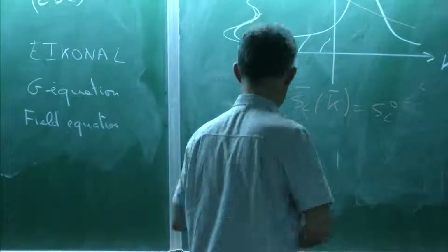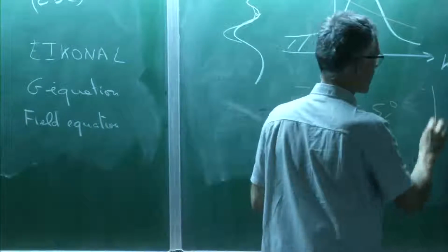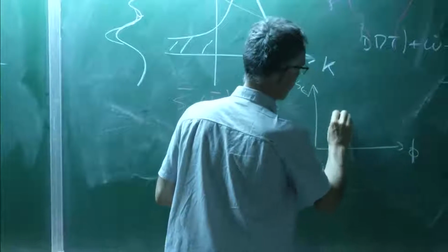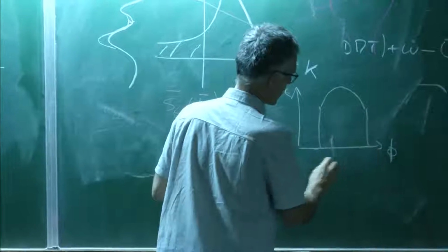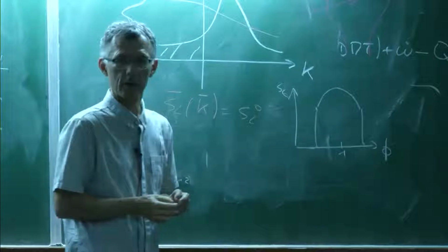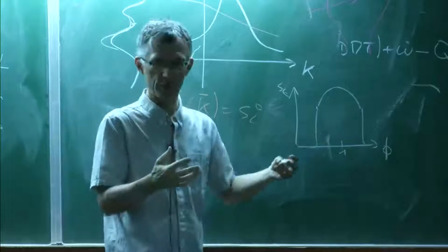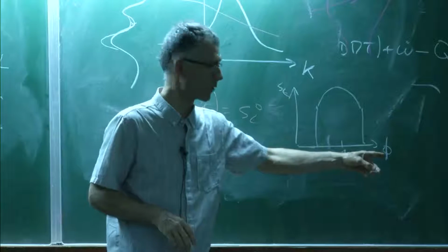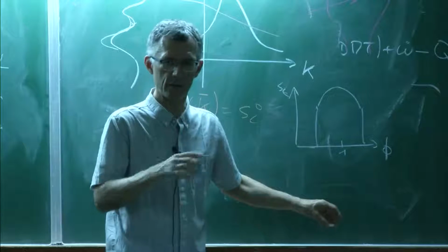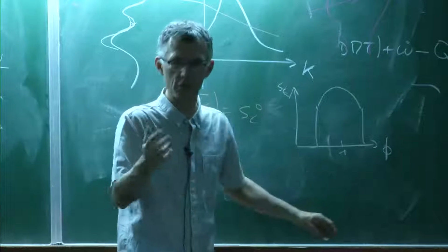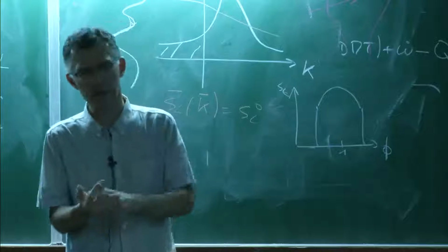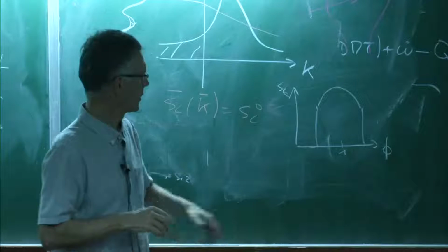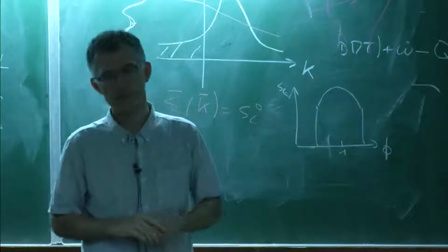So with this curve, SC as a function of local equivalence ratio, like this. If you use that as an input in your code, there's a small trick. You have to be able to find the equivalence ratio. You have to use the mixture fraction. You go through the mixture fraction and you can find the local equivalence ratio at each point, including the burnt gases. And then you go here and you read the SC.